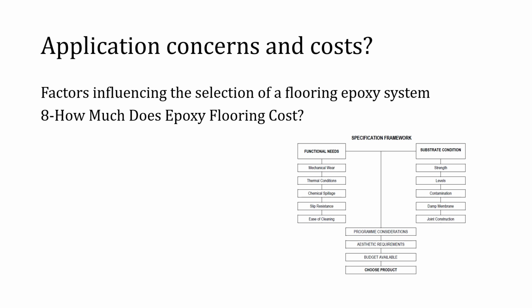In very general terms, the service life will be proportional to the applied thickness of the synthetic resin flooring. However, many operational factors will directly affect the performance, including the severity of trafficking, wheel type and loading, the frequency and efficiency of cleaning, mechanical handling abuse, and other factors. In most industrial facilities, there will be a variety of situations for each of which a different type of synthetic resin flooring will be most appropriate. Conversely, there will be areas where some types are completely inappropriate.